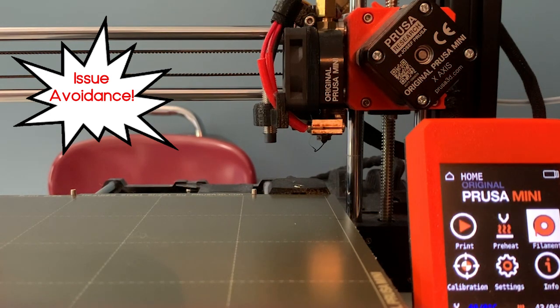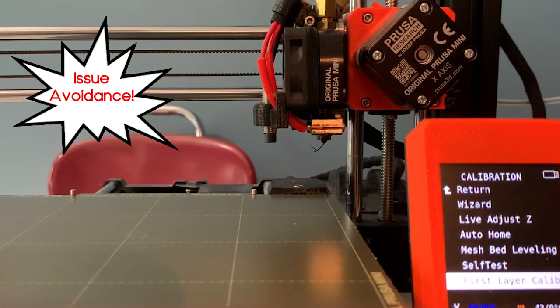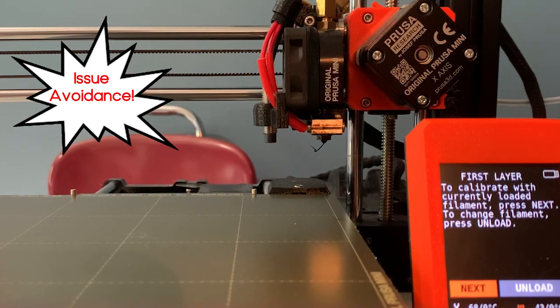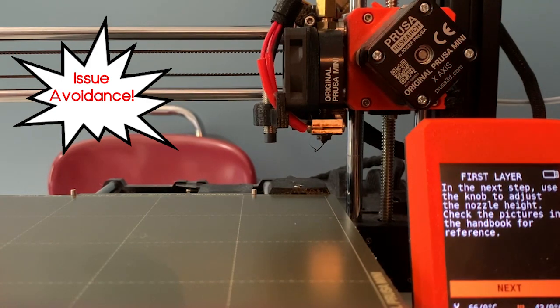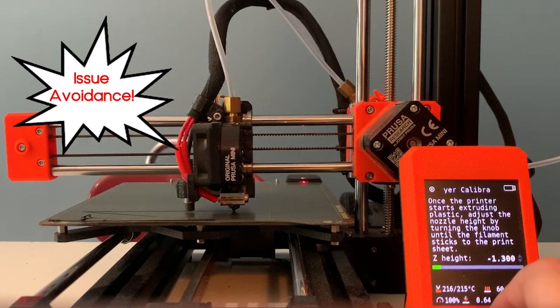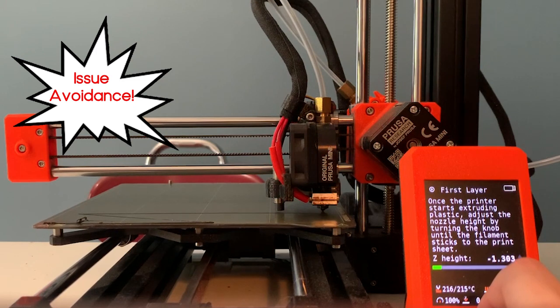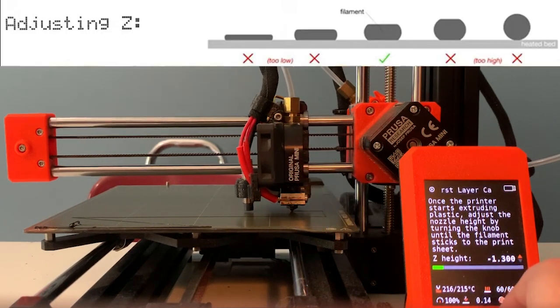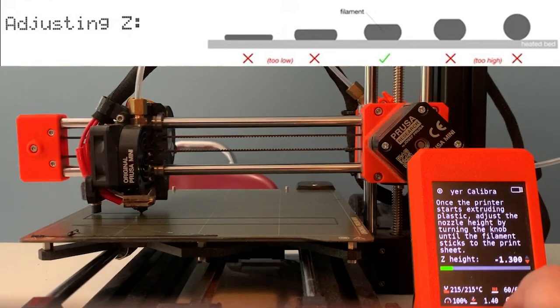To do this, go to Calibration, scroll down to first layer calibration test. Press next, and then hit yes. Once the printer starts extruding plastic, adjust the nozzle height using this knob. Use the chart on the screen to properly calibrate the nozzle height.